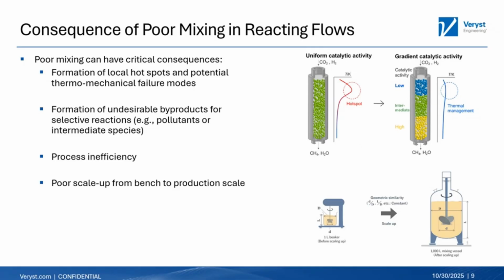Now, beyond that, we see process inefficiency. When we scale up from bench scale to production scale, we find what worked on the bench doesn't work in production, and we need to mix for much longer than we had previously contemplated. In one example, we have a recent client we worked with who, during their scale-up process, had something that mixed in 20 minutes on the bench. They expected a similar mixing blend time in their scaled up system and ended up with something that took 3 days. And so quite the expensive consequence when scale up is not done carefully.